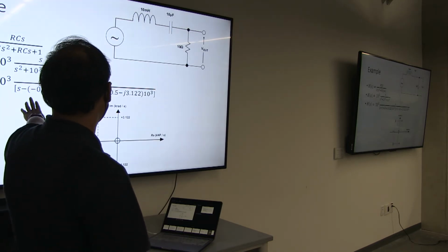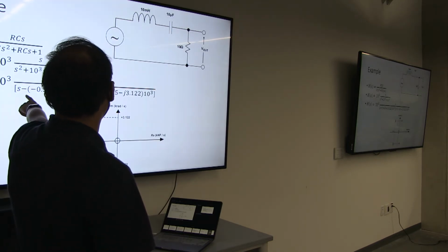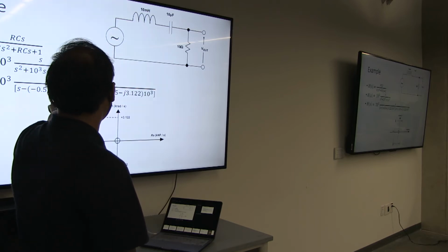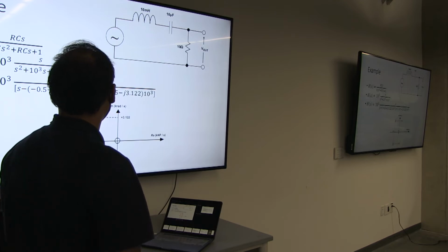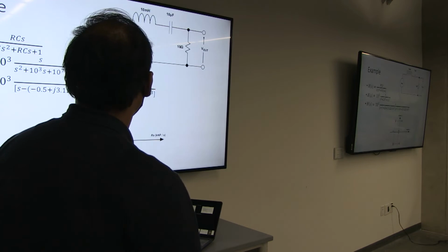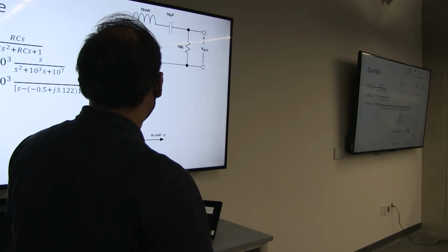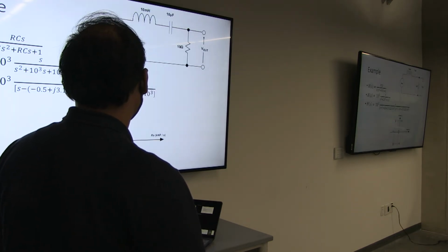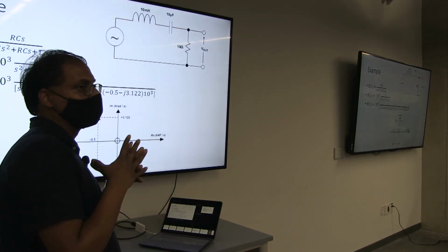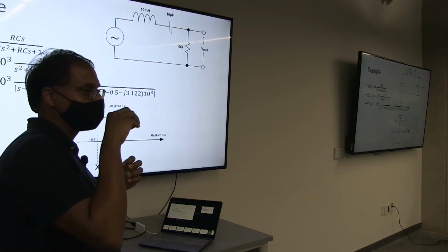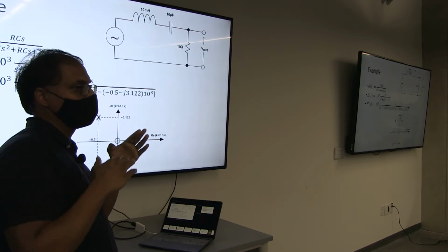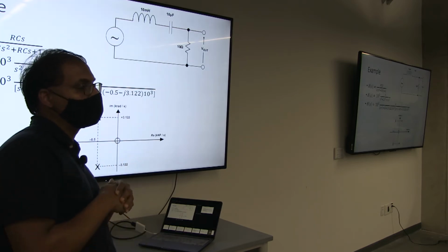So this is S minus, and this will be the j omega frequency. I think this will be a sharp band pass, right? Since we have both poles located at the same point, it will have a rise and then start to roll off at 20 dB per decade.